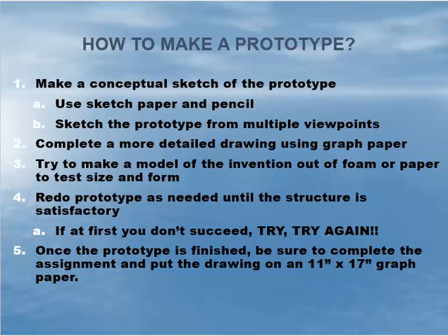For everybody who is in the process of designing and constructing their prototype, there are a number of ways to go about it, but this is the way I would suggest. First, make a conceptual sketch of the prototype. Feel free to use as much sketch paper as you need, and make sure to use pencil and not pen. Sketch that prototype from multiple viewpoints, meaning from the side and also from the back, so you get an understanding of what the prototype looks like.